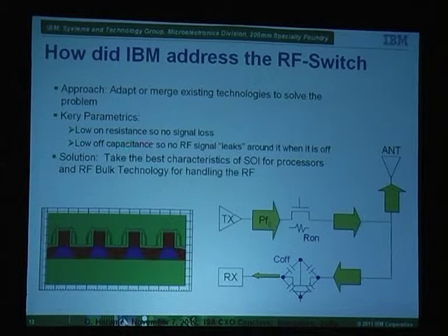Also, the capacitance. SOI has oxide here, silicon here. It has partially depleted, so this is the silicon region. These are the CMOS gates, if you will. And there's a source and a drain. So essentially, the source to drain capacitance is very low. So it reduced capacitance.